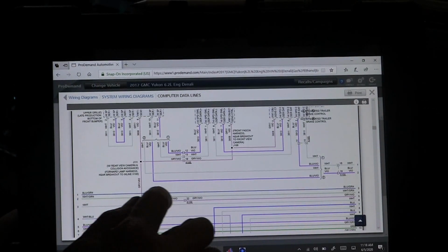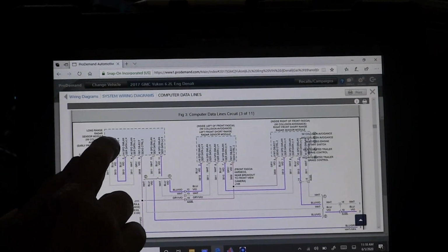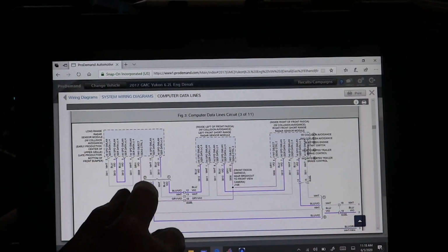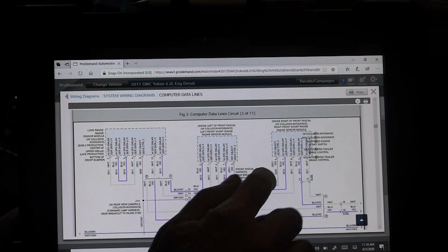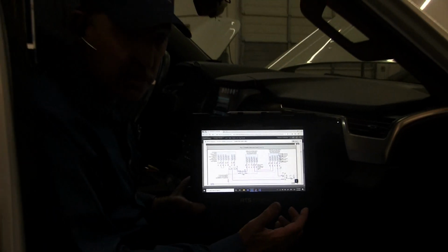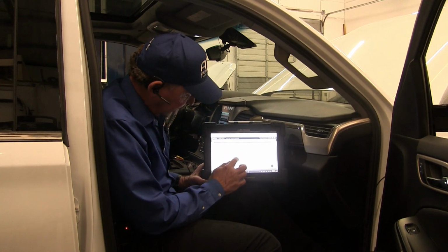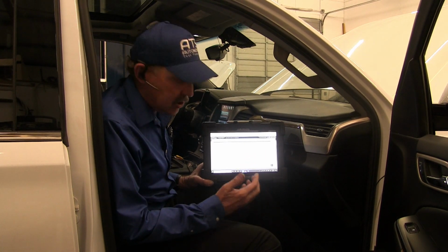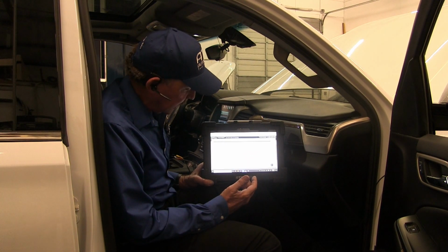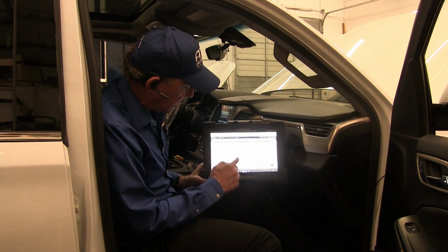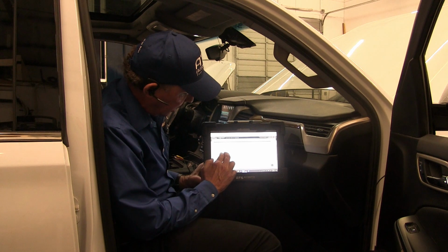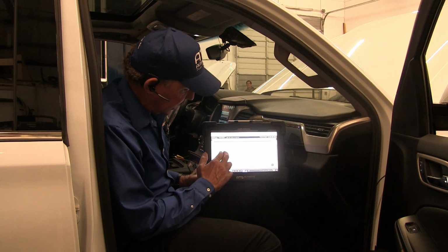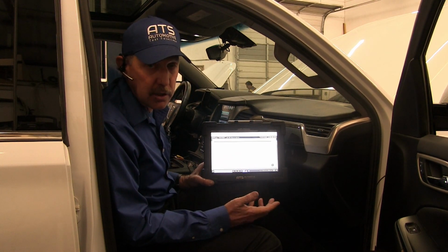And this comes across right here, and it comes up into my long-range radar, short-range radar, and short-range radar. So this is some type of comm line or communications that's saying what my object detection range is. So we'll want to look at that. But the comm lines, it's not saying we have an interruption in communication to any of the radars. It says that the EBC can't talk to the front camera. And the only comm lines I have on this diagram is showing that I have 2 CAN lines each. So there's 2 high CANs and 2 low CANs.